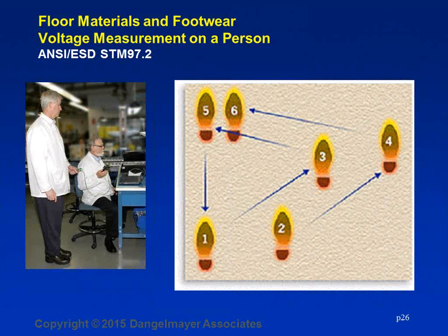So in this slide, you can see Ted Dangelmeyer is holding the electrode, and Arnie Steinem, who you'll hear from in a minute, is holding the charge plate monitor and gathering the data. And we have a schematic of a possible walking pattern. This is often known as the ESD shuffle. The idea is that you would be stepping backwards and forwards and side to side as somebody might step while they're doing work in the work area.